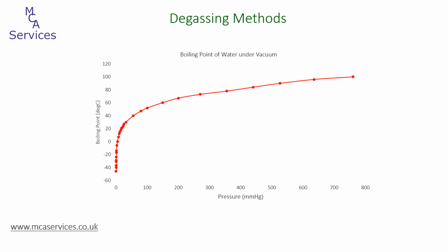Now, a good vacuum pump and vacuum degassing system should certainly generate a pressure of around about 50 microns mercury, or 0.05 millimeters mercury on the x-axis scale here. At such a pressure, water boils at around about -50 degrees, and we can then remove moisture from a sample without applying any heat at all. And of course this becomes particularly suitable when we're analysing temperature sensitive materials.